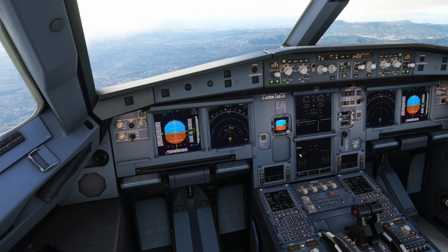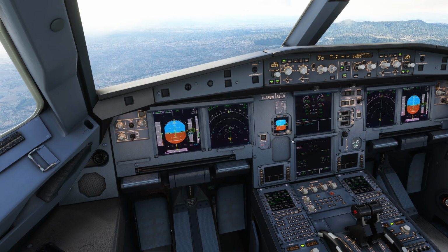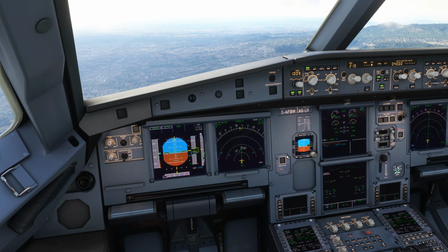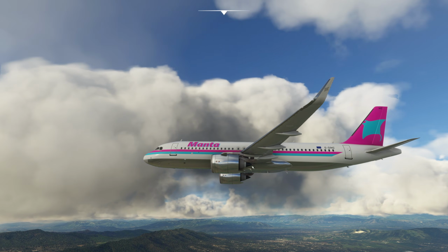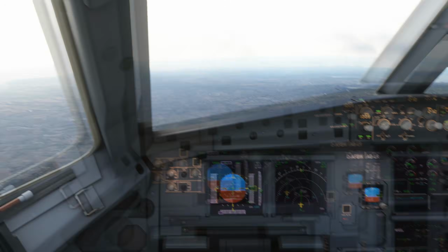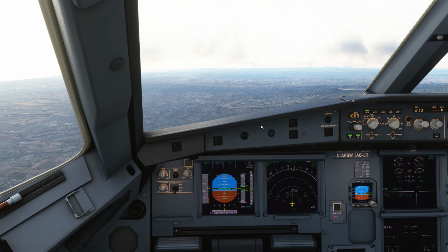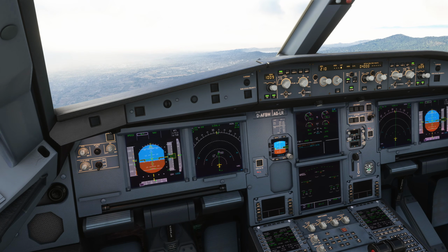The gear doors are going to remain open after we've done this, so we will have a huge fuel penalty, because when those gear doors are down underneath the aircraft, you've got big holes where the gear sits when it's up. So yeah, a very huge drag penalty. Right, let's get ourselves onto the approach, and as I said, this is something you would plan in advance, and I'll show you that in action.